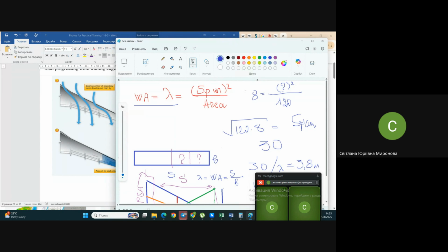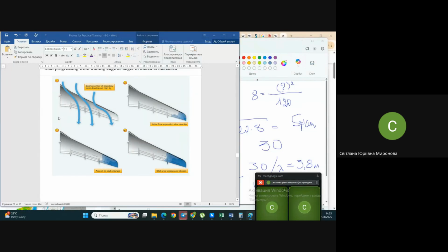Knowing your calculated area, you may say what the span is. Knowing the area and span, you may calculate either the mean chord or even immediately the root and tip chord. You may appoint it, or you may use one additional relative, dimensionless parameter, which is called narrowing of the wing, and it also means that you need to analyze your statistical information.